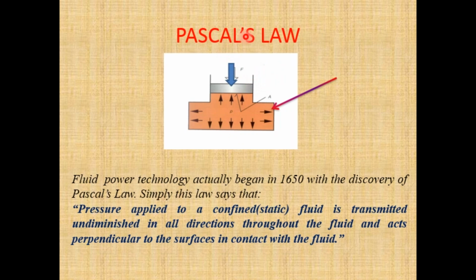This Pascal's law is the basic principle behind the working of any hydraulic or pneumatic system. If you imagine a JCB, the person sitting and operating it is just moving a small lever by hand, and he is not applying much pressure on it. With a very small amount of force he moves the lever, and that is able to lift a heavy load. So how is it happening? That is happening because of this particular law, which is called Pascal's law.